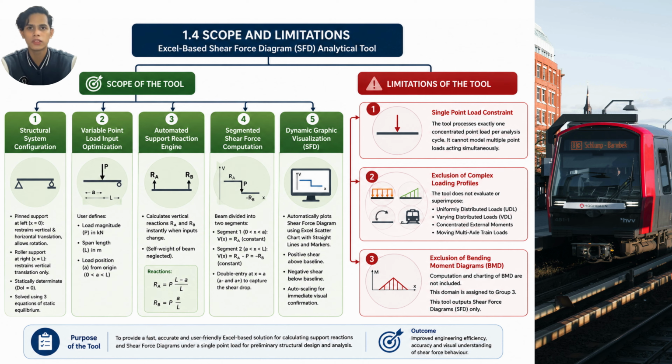Now, moving on to the limitation of the tool. First, the tool is limited to only one concentrated point load per analysis. It cannot analyze multiple point load situations. Second, it does not support more complex load conditions, such as uniformly distributed load, varying distributed load, external moment, or moving train load that are commonly found in railway structure.